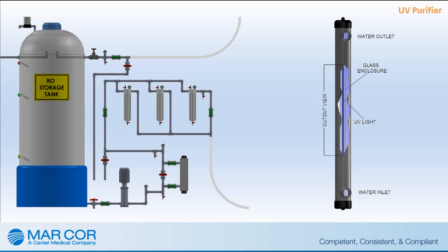The byproduct of the UV killing bacteria is that the outer membrane of these bacteria break apart. The byproduct of this outer membrane disintegration are referred to as endotoxins. These endotoxins can elicit a very strong immune response and cause very severe reactions in patients. Because of this negative patient response to endotoxins, the UV must be followed by a pyrogen filter, endotoxin filter, and/or ultrafilter to trap any endotoxins produced as a result of the UV light killing bacteria.